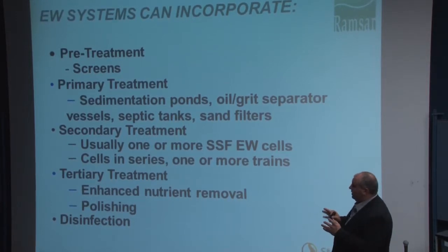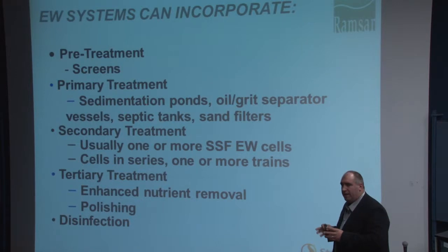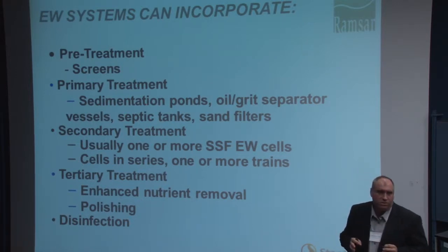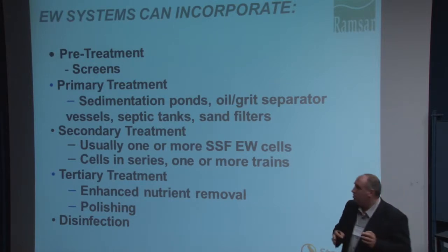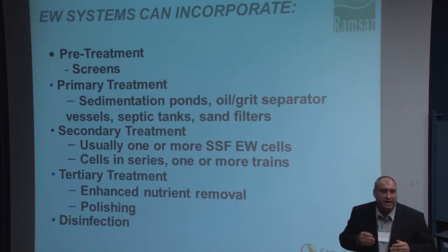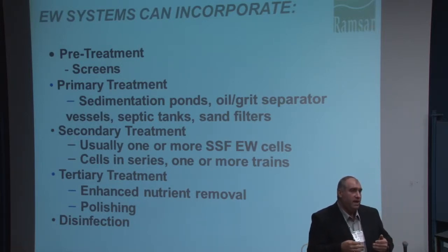So in most cases, when you're dealing with a waste stream that has a high particulate load, a high TSS load, then you need to have a cell or a phase before it gets to that engineered wetland that will take down that particulate.